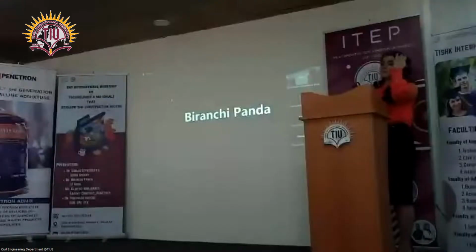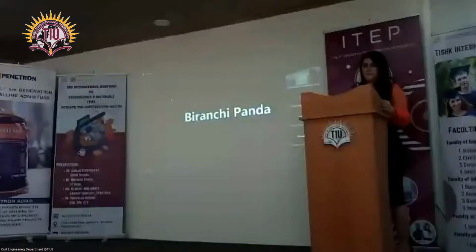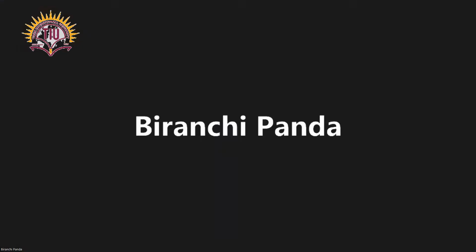By default, you will get some surface pattern because of the layer by layer printing. But if you want to avoid that and get a better surface finish, it is possible to have some kind of surface layering nozzle where you can clear all the extra material and smoothen the surface like we do in regular construction. That is possible. I have seen some printing video where they have added some kind of flap to the nozzle to smoothen it.